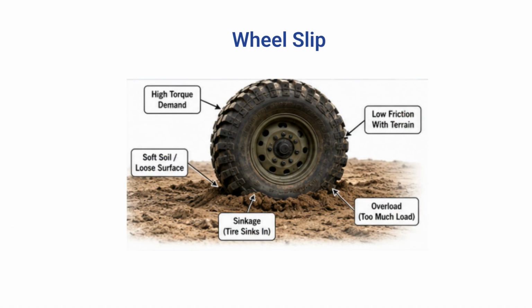This image explains wheel slip, the difference between how far a tyre should travel based on its rotation and how far the vehicle actually moves. Some slip is normal, especially on loose terrain. With low or controlled slip, most of the tyre's rotation becomes useful forward motion. This provides good traction, better efficiency, and stable vehicle control.